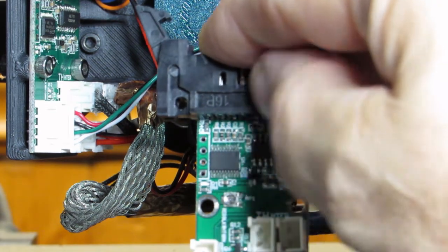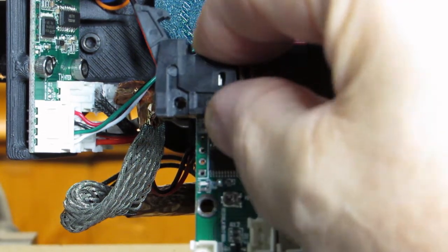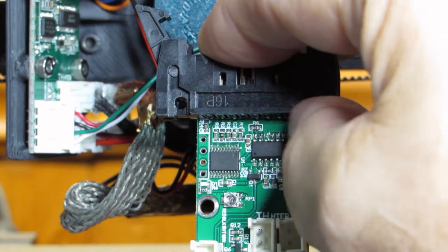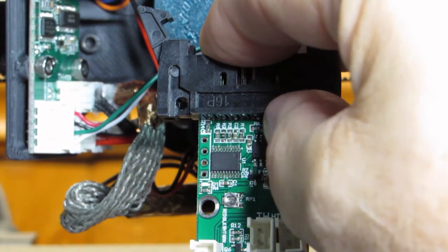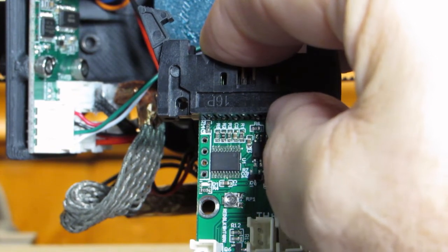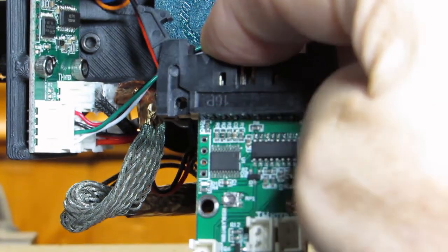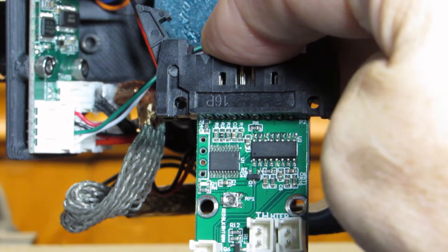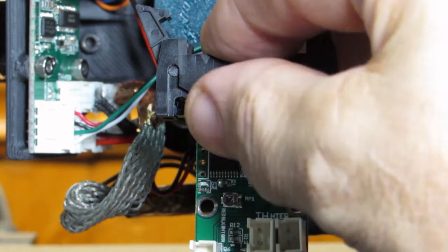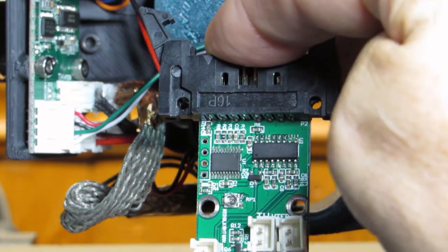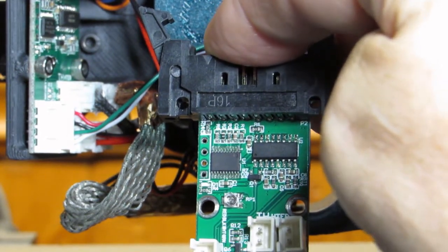That one sends a value into the processor. The strain gauge reader sends a signal in, and the software in there compares the two and makes a decision. And when it decides that, yep, that's the bed, the little blue light comes on and it sends a signal down to Marlin saying we've hit something.